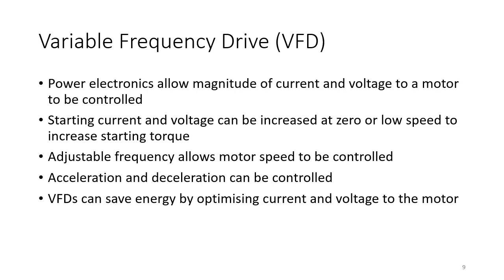You can't accelerate faster than the torque of the motor can deliver to the actual mechanical equipment that's fitted. But you often want to accelerate slower than that, because you don't want to damage the mechanics. You want to avoid stresses on the gearbox and any other mechanical components fitted. So often it's desirable to have a slower acceleration than is actually possible. And that's something else that a VFD can handle.